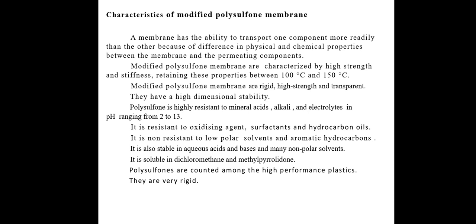Polysulfone is highly resistant to mineral acids, alkali, and electrolytes in pH ranging from 2 to 13. It is resistant to oxidizing agents, surfactants, and hydrocarbon oils. It is non-resistant to low polymer solvents and aromatic hydrocarbons.